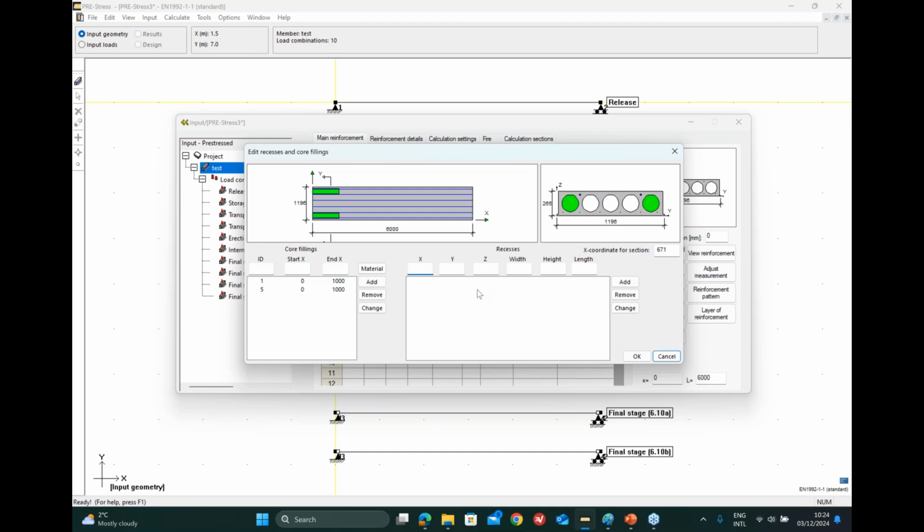Following the same principle, you do the cutout. So you give it the starting coordinate, 1000, maybe make it 3000, so it can be more in the middle, and then 200, Z0, weight 150, height 265, length 150. And I have created a cutout, right?